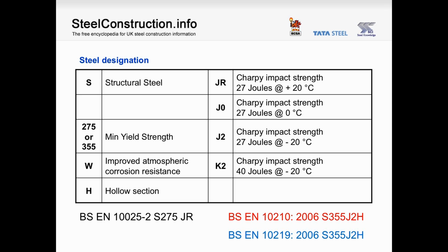That is, we haven't informed the fabricator whether the hollow section is hot finished or cold formed. If you cast your mind back, there can be a very significant difference in the capacity of these two products. An alternative, of course, is to specify product. For instance, Tata Steel's hot finished hollow section is Celsius and the cold formed product is Hybox.